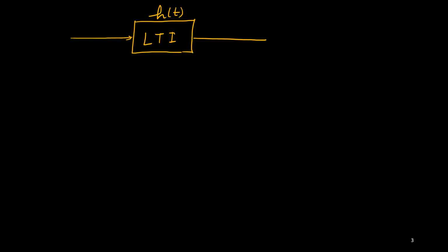First you should have this knowledge that if you have an LTI system, suppose this is LTI, and its impulse response h(t), and here if the input signal x(t) is of this form, A cos 2 pi f naught t, one cos signal or a sine signal, whatever it is, then the output signal y(t) is again sinusoidal and the frequency will remain the same, only the magnitude is modified and the phase is also modified.